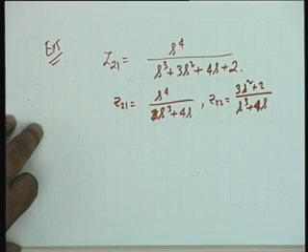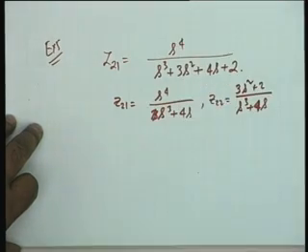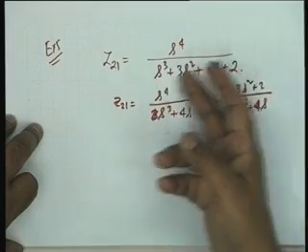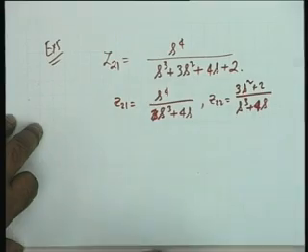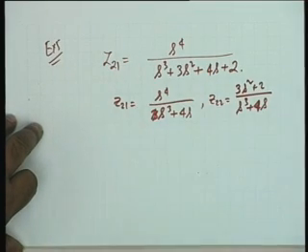So degree of denominator is 3, degree of numerator is 4. Pardon me? Poles are not on j omega, it cannot be on j omega axis. It is a Hurwitz polynomial. Well, these poles are on the j omega axis. s times s square plus 4. Yes, one is the origin, one is plus minus j. Any other?